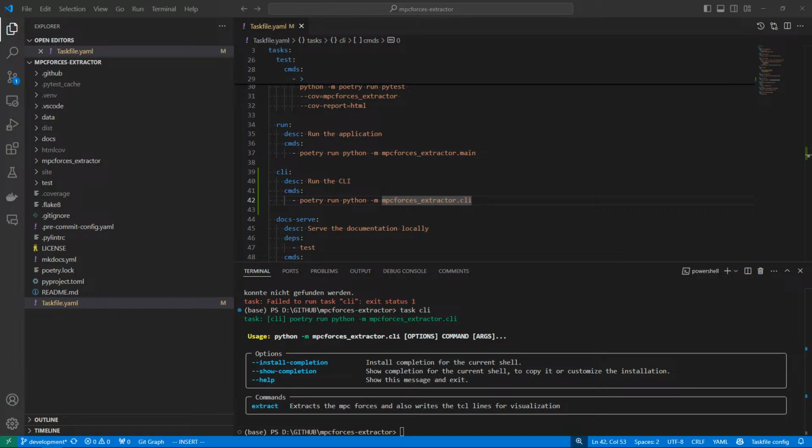Let me give you a simple example. Altair itself, the HyperMesh product developer, they have something like a similarity tool which detects similar parts in a model. And the way they're doing that, at least to my knowledge, is by checking the moments of inertia and the higher moments of a part.